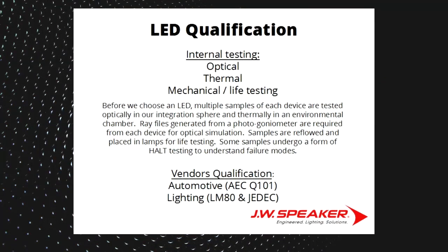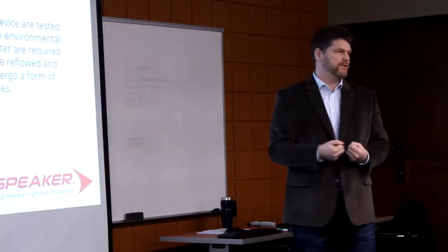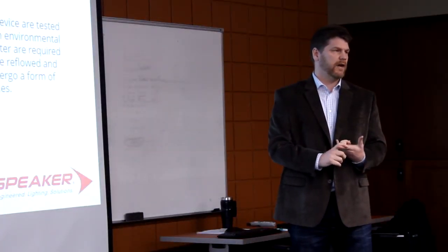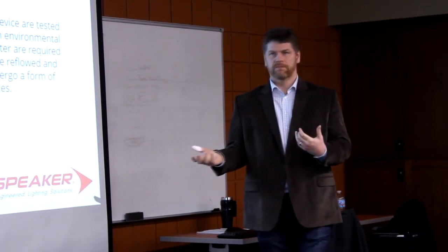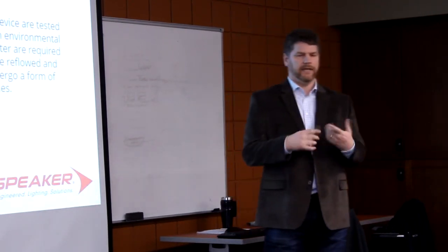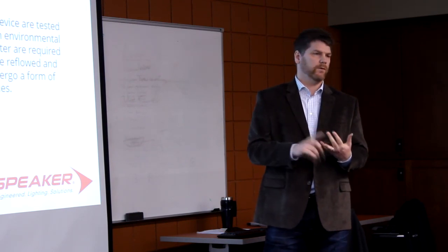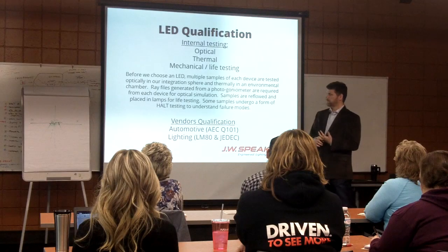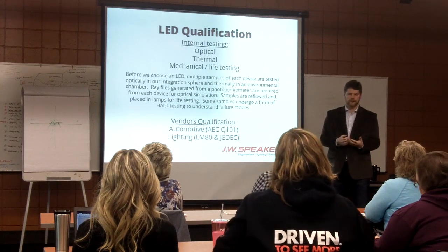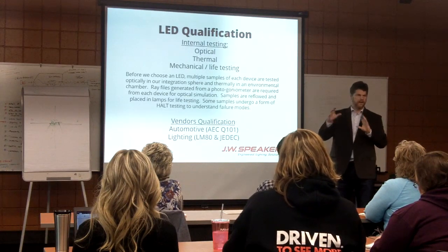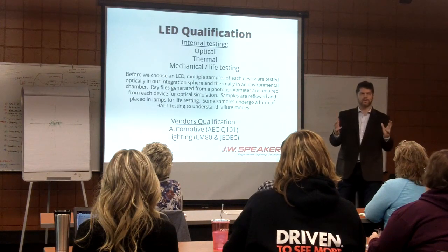So when we choose an LED, the first thing is we don't always trust the manufacturer of the LED because different manufacturers have different test methods. We like to get samples ourselves. We like to mount them ourselves with our SMT processes. And then we use our photo lab to qualify the LED by taking flux measurements, sometimes color measurements, and the forward voltage measurements. And then I put it into a little mathematical model I have to compare it to other LEDs we've measured and understand what its worth is. And then I tell the manufacturer, I'm willing to pay this for that LED, and hopefully get that price or lower.